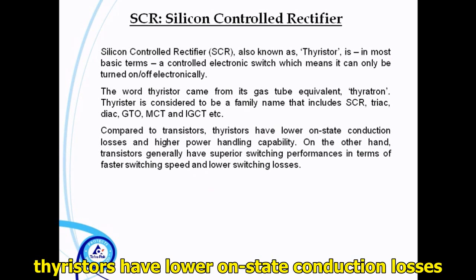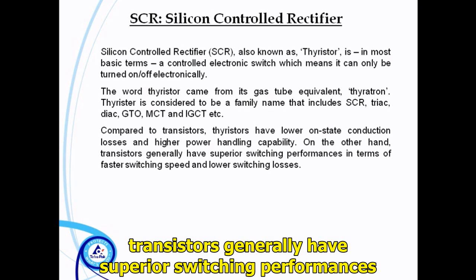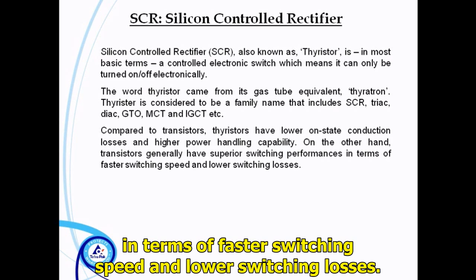for SCR. Compared to transistors, thyristors have lower on-state conduction losses and higher power handling capability. On the other hand, transistors generally have superior switching performances in terms of faster switching speed and lower switching losses.